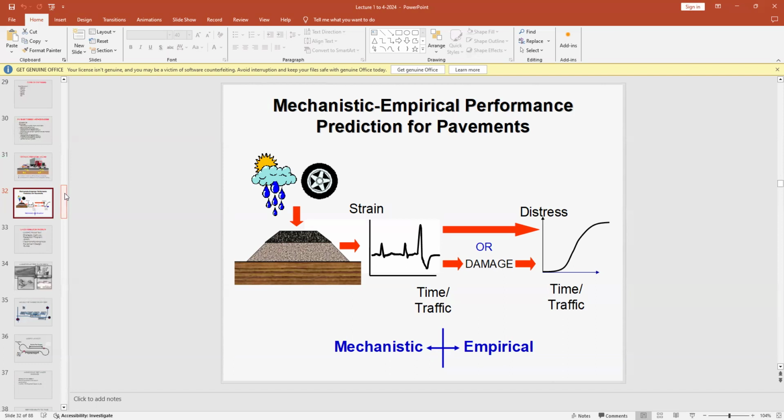Then, how do you cater for the water, how do you cater for the drainage? Because water from the raining season will come on the pavement. And the more it will retain on the pavement, the more damage it will do. Again, if you design a thicker pavement, you will have less water damage.